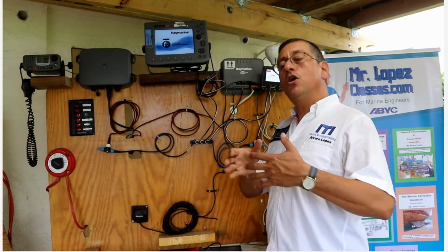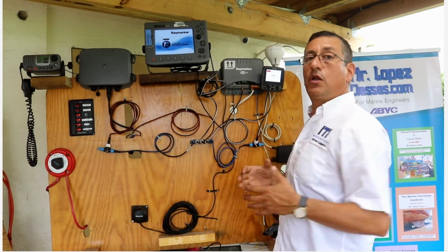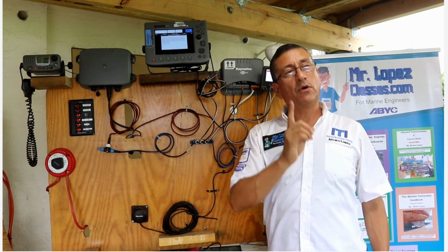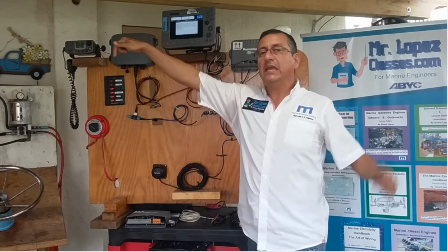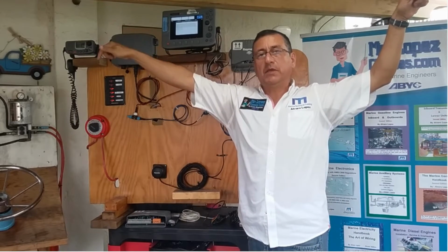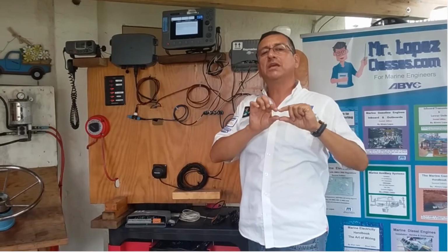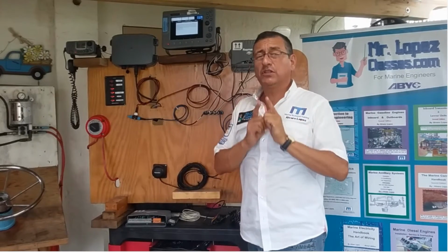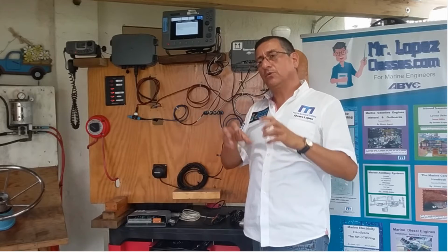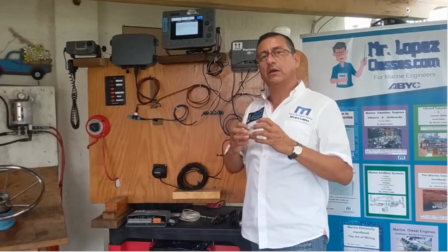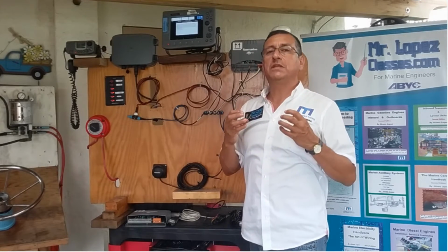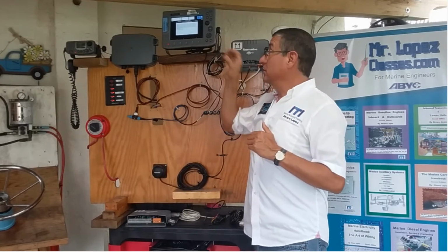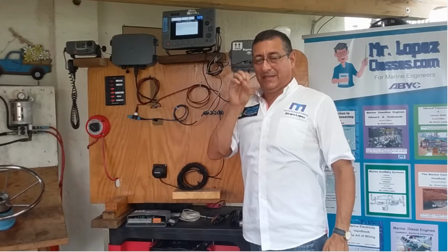When you have a long backbone, the recommendation is one source of power in the middle and one at each end, at the beginning and at the end, in order to keep the voltage stable and equal in the backbone. The voltage drop is another critical factor that we are going to talk about right now, and we are going to calculate how much the maximum voltage drop should be in order to avoid an inconvenience on the computer,